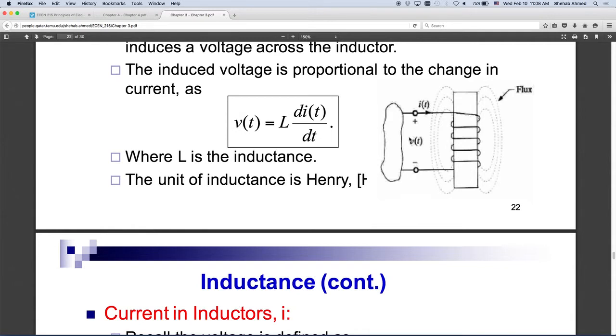What happens if I raise the voltage in that case? I put a power supply and I raise the voltage. Current will increase. Of course, current will increase because it's seeing some impedance of a certain value. But this current increase is not going to correspond to an increase in the flux that you have. So you will see an increase in current, but it will not be increasing flux.